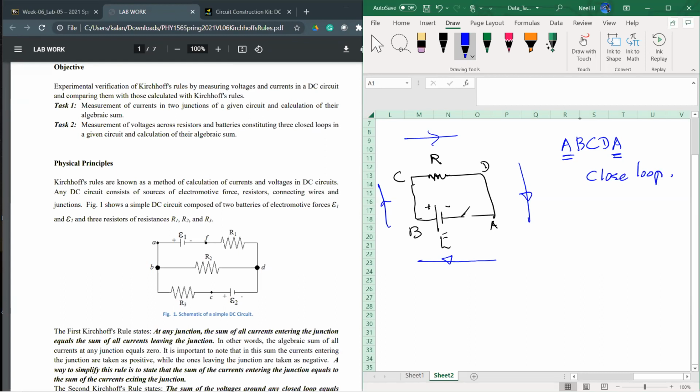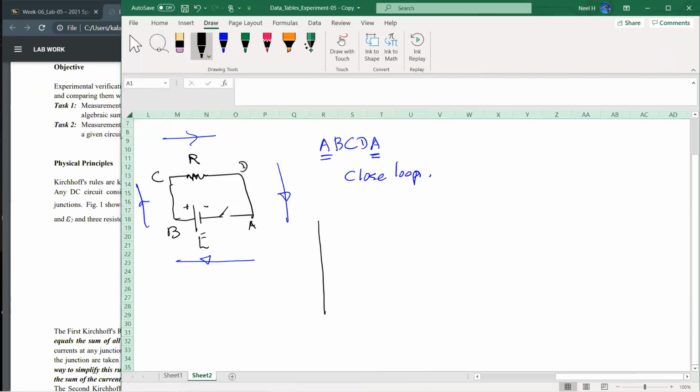Now as I move through that, we're going to look at how the voltage is actually adding and dropping across this path. Let's consider this is the path direction, and this is the voltage. I'm starting at A. Point A is directly connected to this point right here, 0, which means point A voltage is 0. There's no voltage at all. Then I go from A to B. This side is positive, so the voltage increases rapidly to some maximum value, that is the battery voltage E. And then B to C, it's a wire. There's no voltage drop. It remains as it is.